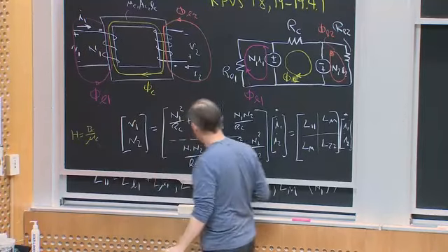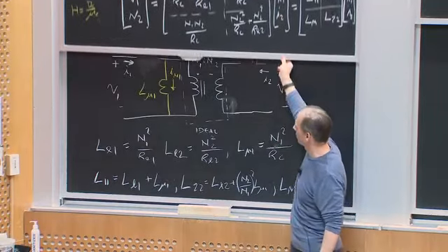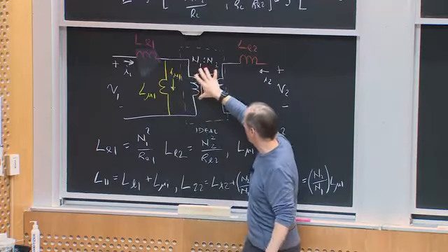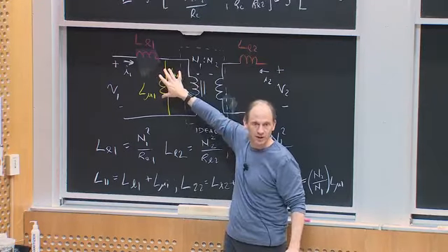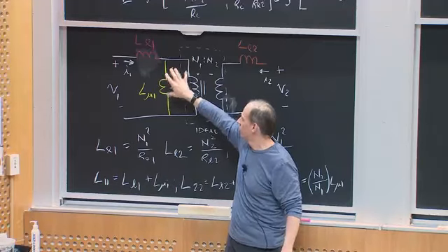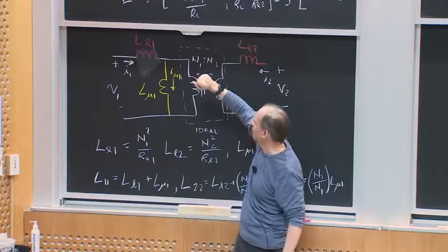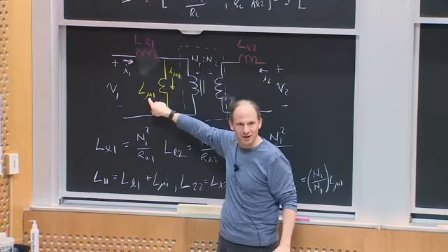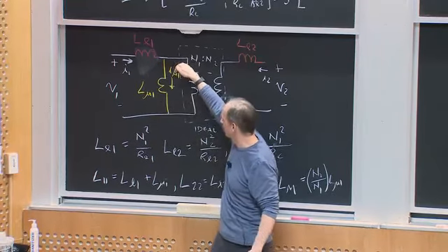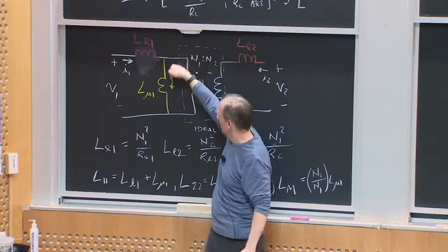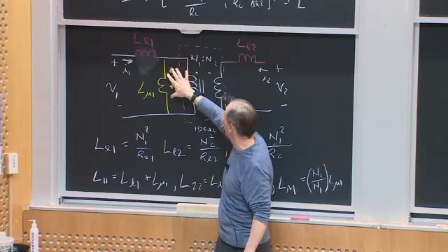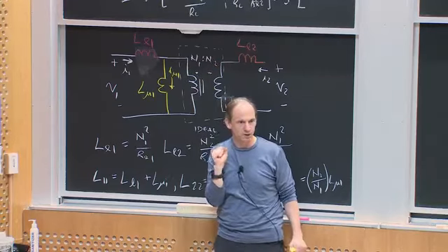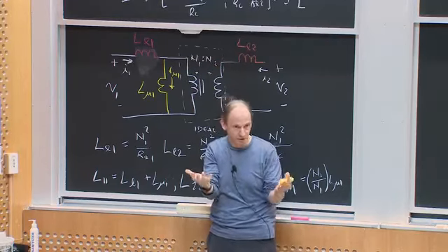And the way that pops into the circuit model is through this inductance that appears across the ideal transformer. The difference between having infinite permeability, where you have no energy storage, or equivalently an infinite magnetizing inductance that carries no current, is that I get a finite magnetizing inductance that has a current that ends up being a mismatch between the ideal turns ratio of the transformer, or the ideal transformation ratio of an ideal transformer.